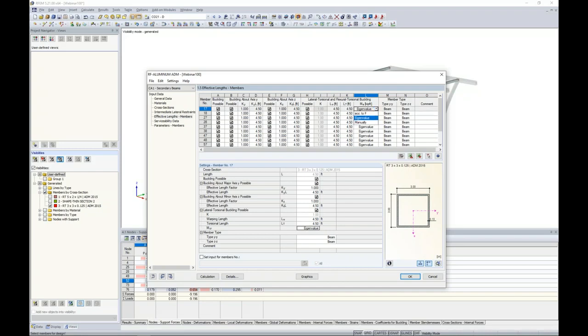Now, the critical buckling moment can be determined by default by an eigenvalue analysis. So this is a much more theoretical approach where we are essentially going to consider 4 degrees of freedom on either side of the beam member. Now, our assumptions with this is that the member is laterally and torsionally restrained at the ends, but free to warp. So if these are your constraints and you want to run it according to an eigenvalue analysis to determine the critical buckling moment, you can leave this as default.